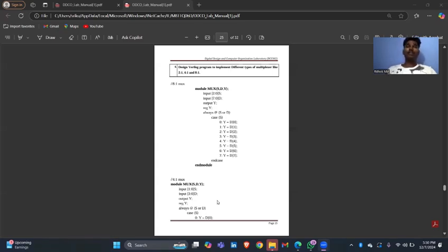And then case is used because when we consider a 4 is to 1 multiplexer, as we all know, there will be 4 input lines. Hence there are 4 possible combinations, so we can send 00, 01, 10 or 11 to the selector pins to select one among the 4 inputs as an output. So here are the following cases, that is 0 is to Y is equal to D of 0. Its purpose is, if S is 0, and the binary value of 0 is 00, the output Y is assigned the value of D of 0.